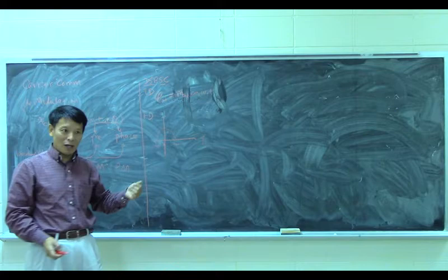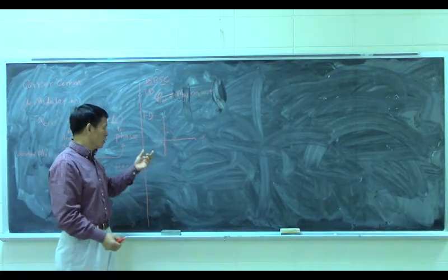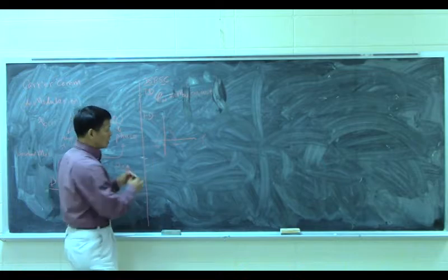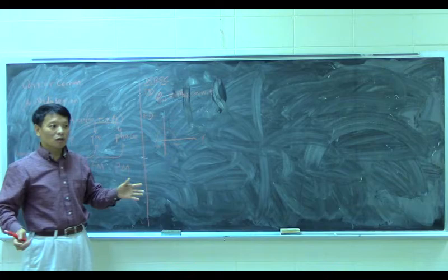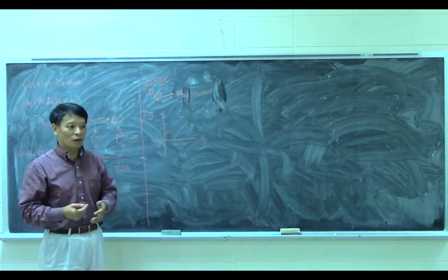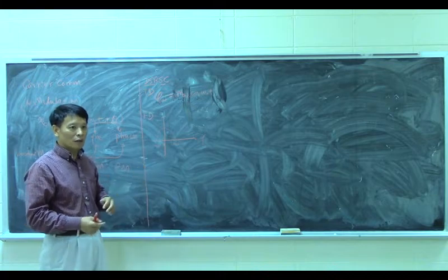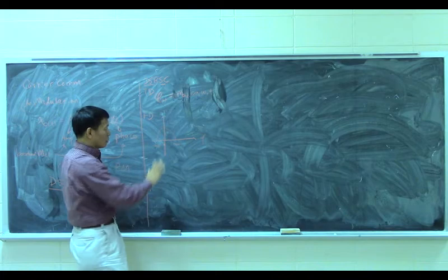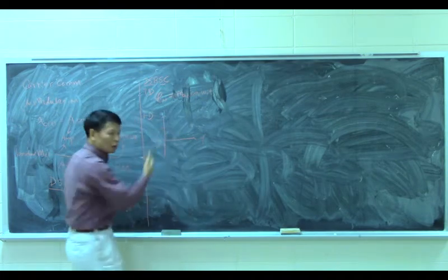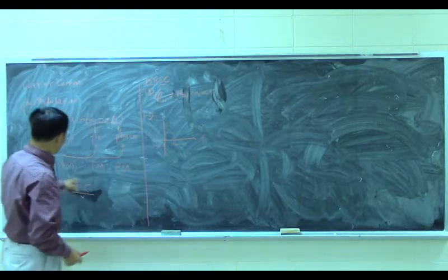So for example, in the lab, if you observe this signal with the oscilloscope or spectrum analyzer, you can only see this part. You cannot see the whole thing, because there's no such thing as negative frequency in real life. This is only for mathematical simplification. So this one will be symmetric. So for the power, you just flip this part, add it to this one. That's all.